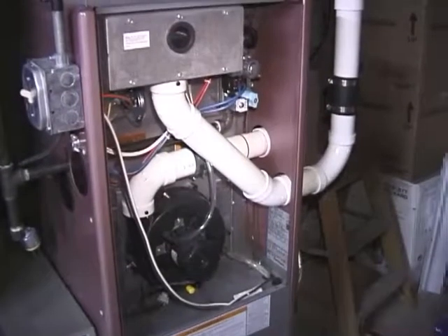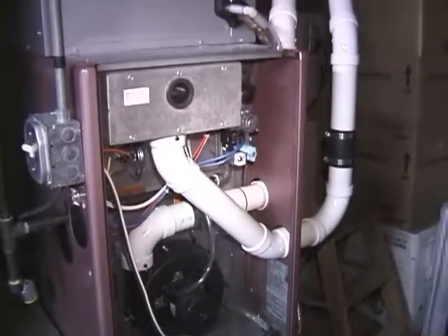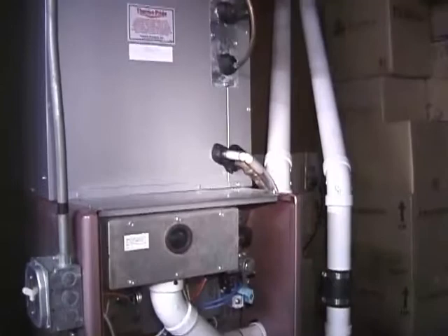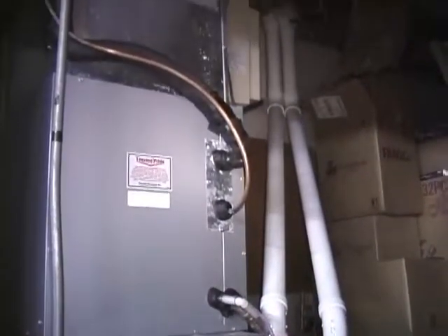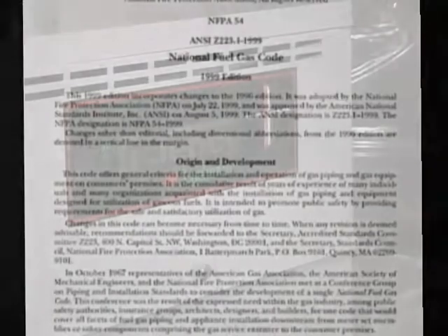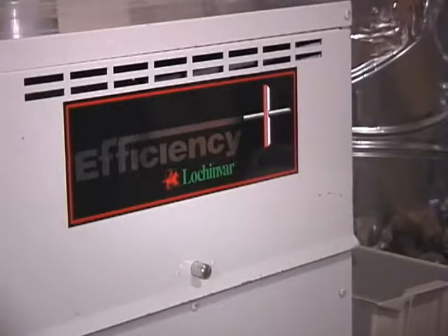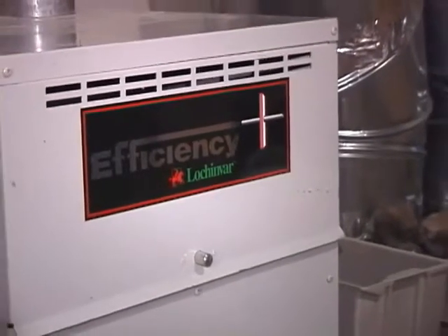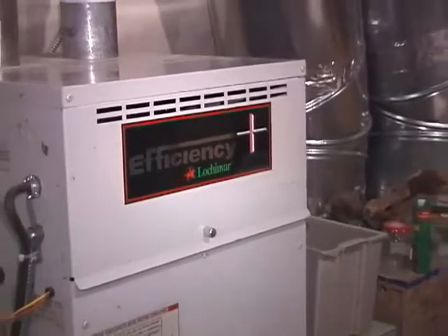First of all, it's important to understand the differences in the ways various appliances are designed to vent their byproducts of combustion. The development of more efficient combustion appliances has resulted in many new designs that have different venting requirements. Therefore, in the late 1980s, the American National Standards Institute, ANSI, along with the American Gas Association, established criteria for designating vented combustion appliances as one of four categories.